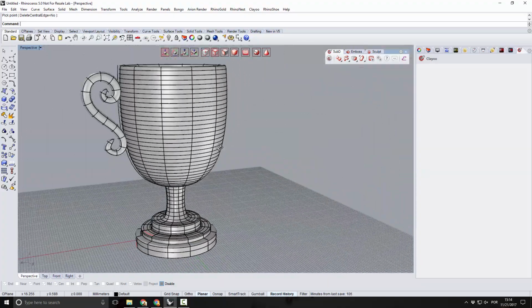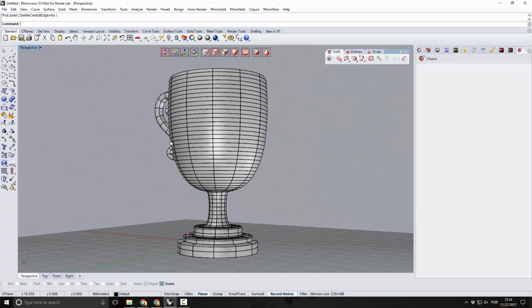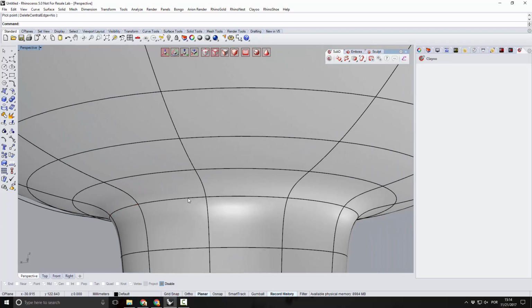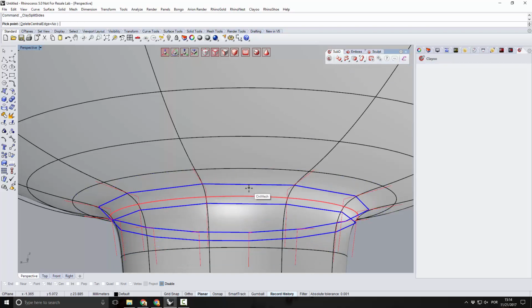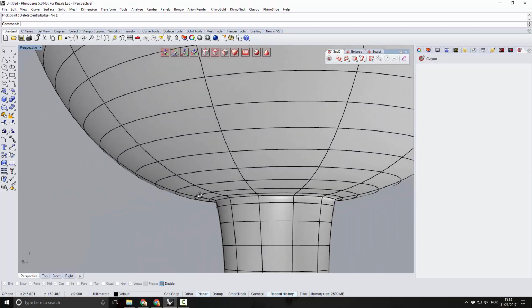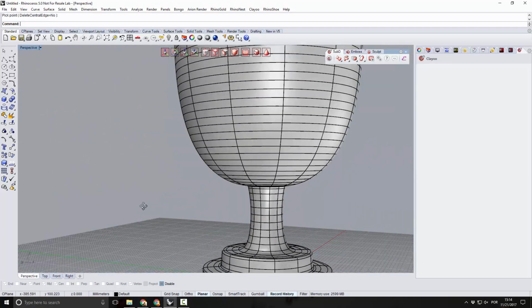So now maybe in here we can also make it a sharp edge, so just select the loop and split sides will make it. Just select the division very close to the original edge, and this will be the result.